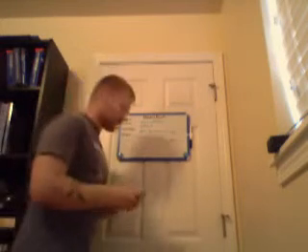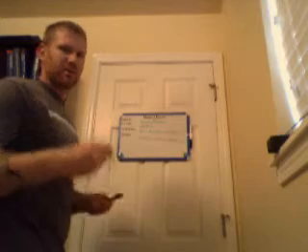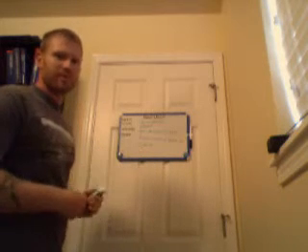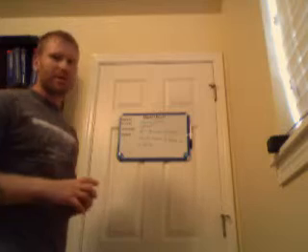So with any two of these three things, we can figure out the other. So our basic weight and balance calculation is weight times arm equals moment. So that's your basic calculation method. And then once you have total moment for your whole aircraft as it is, full fuel, everything you want to fly with, you just divide that by your total weight, and you can get your center of gravity, which is the arm of the aircraft at that point.